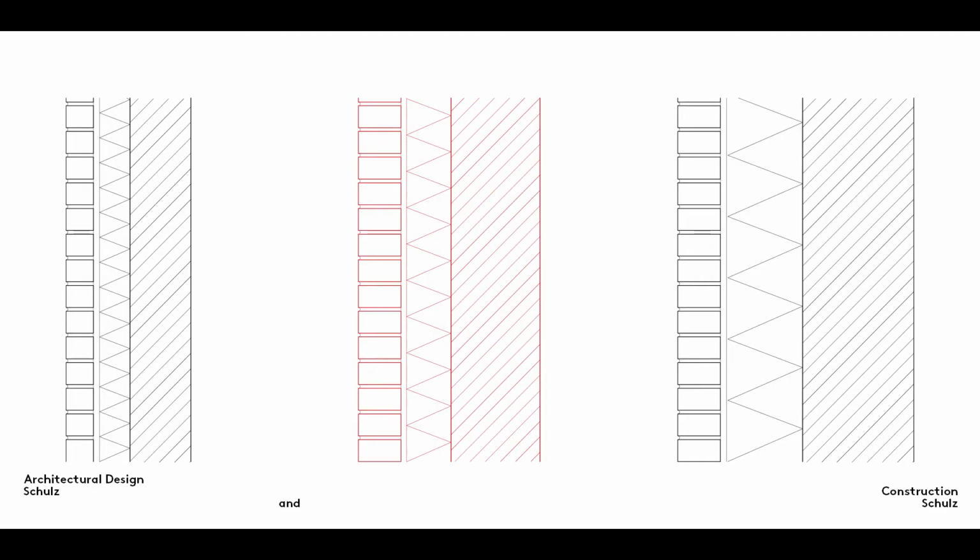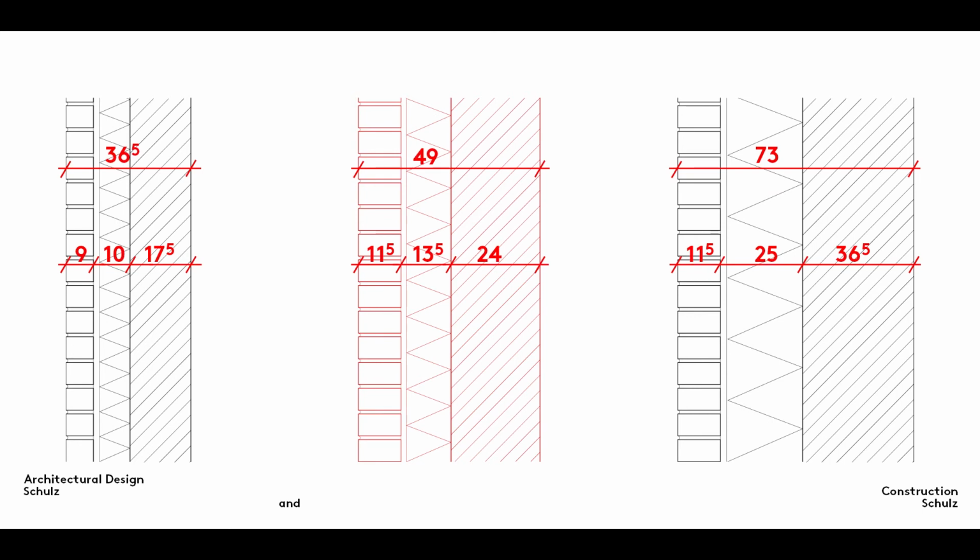If we take a look at the minimum and maximum layer thicknesses for double skin walls, we can see that the bricks in the facing skin must be 11.5 cm thick to follow the octametric system. The thickness of the insulating layer may mean that the dimensions of the load-bearing skin are no longer necessarily multiples of 1/8 of a meter. This can only be guaranteed if the insulating layer corresponds to the dimensions of an octametric cavity, that is to say, it is 13.5 cm or 26 cm thick.